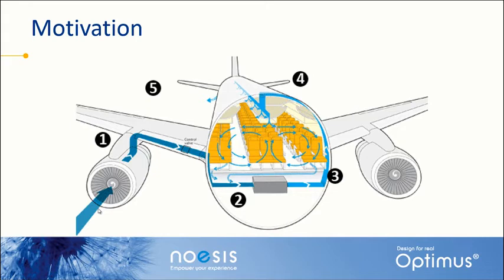There is typically an amount of free air or fresh air that's allowed into the cabin. Typically, this air is actually regulated. The percentage of air that comes into the cabin is regulated. For instance, an aircraft may be required to have, say, 5% fresh air allowed into the cabin.